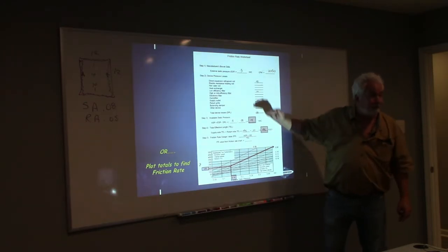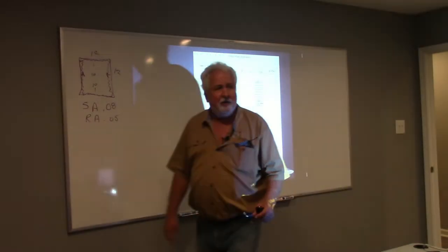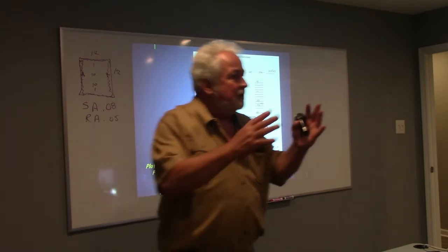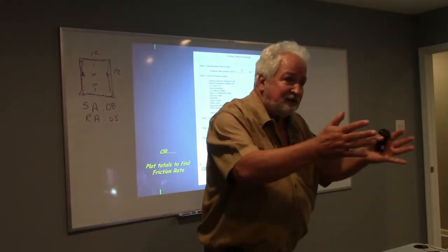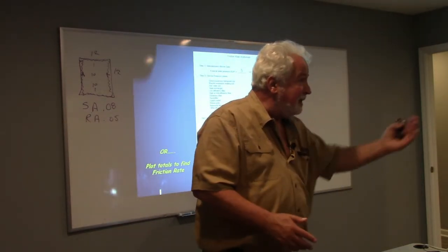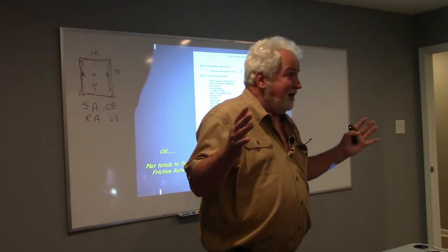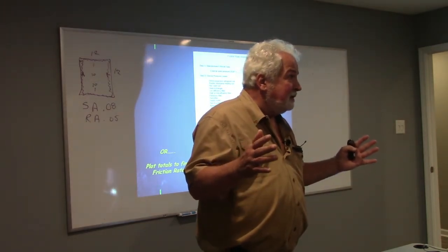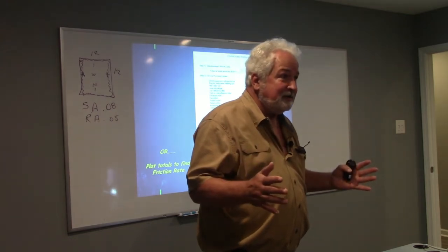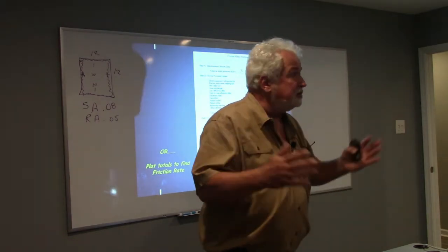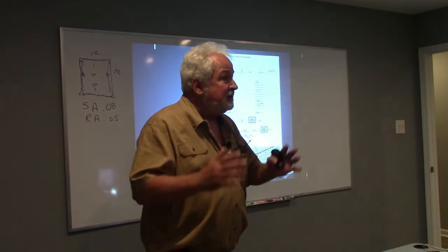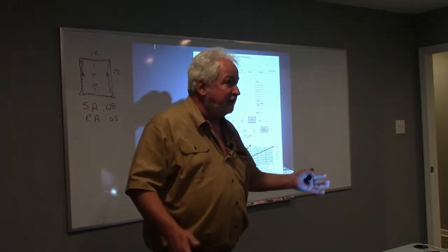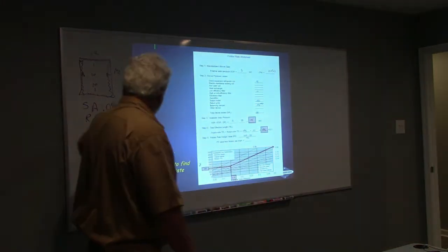You follow? Good. So what is our concentration when we start putting all this ductwork together? Make the ductwork large enough, make it straight enough, and get a filter that I can get enough air through. A MERV 16 is a great filter, but so is a brick. I just can't get any air through it. So we need to get the air through. Our concentration is to get the best airflow through the ductwork and the fittings. Fair? Okay, so that's where we got the 0.08.